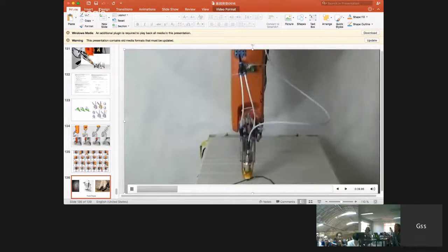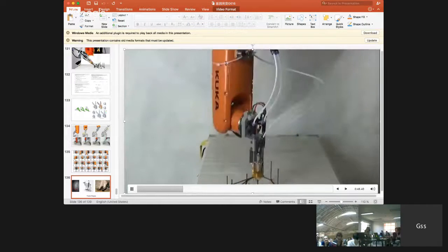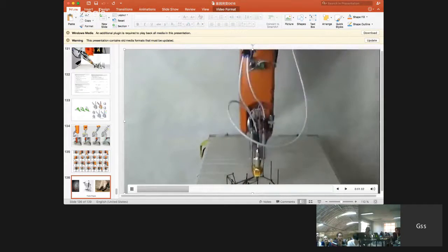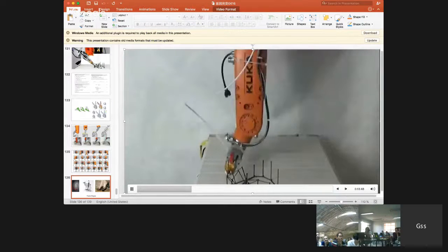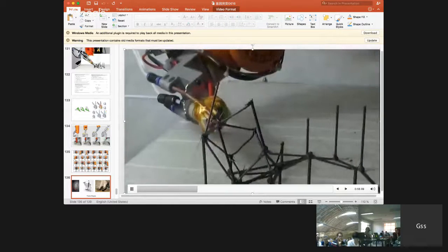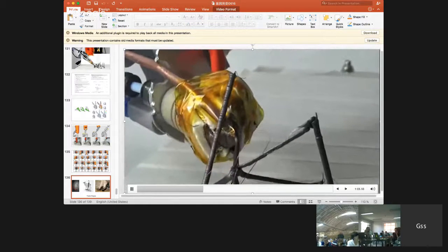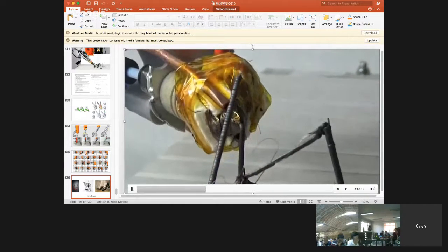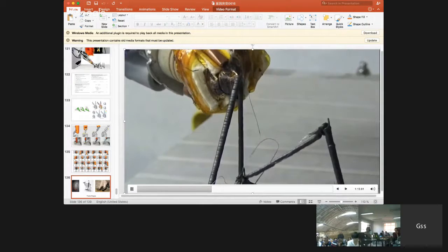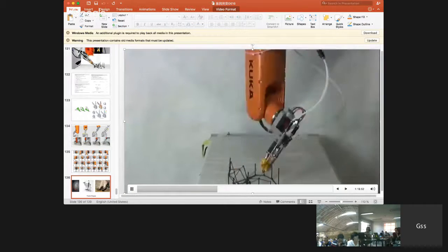In this work, we propose a fabrication sequence design algorithm to search fabrication sequences for general frame shape fabrication. The general fabrication sequence is collision-free and guarantees that the printed structures have small deformations during the whole fabrication process. In our experimental setup, we allow the extrusion head to have different orientations for fabricating different frame struts. During the whole fabrication process, the printed parts should be in a static equilibrium, and the extruder should avoid colliding with the previously printed parts when it moves.